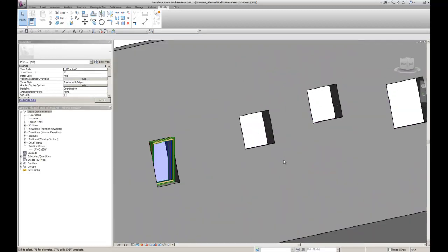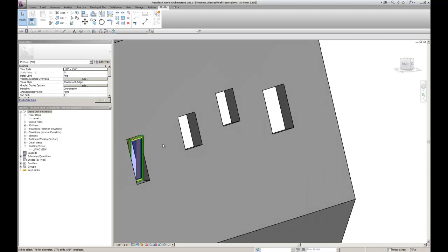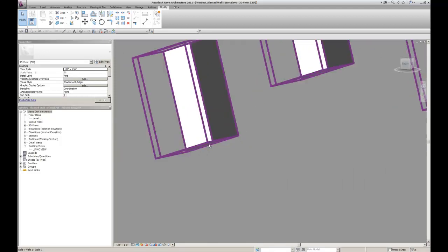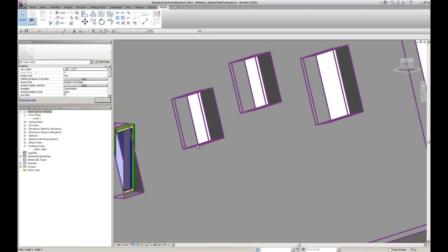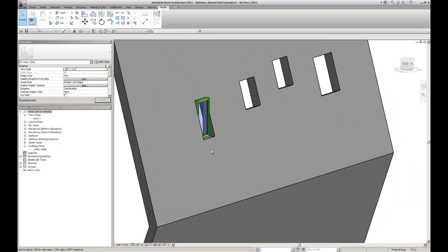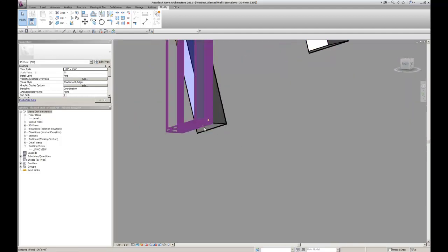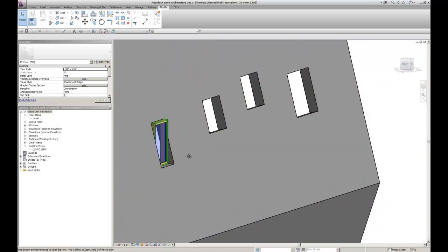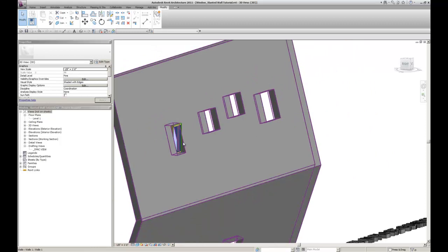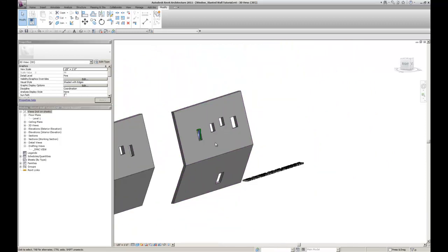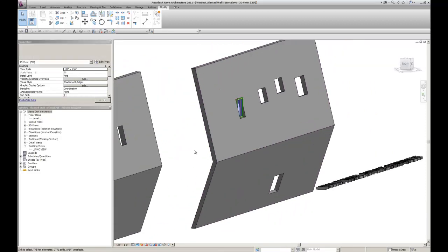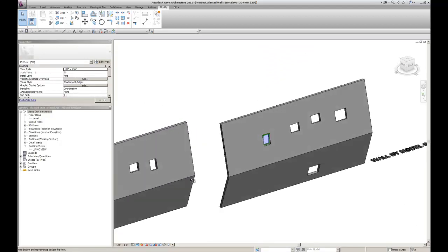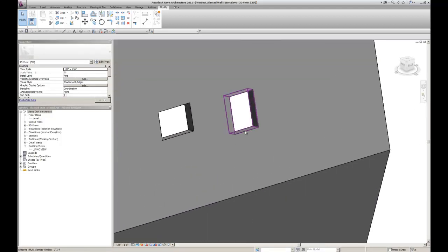So one issue to think about is that this type of family is following the angle of the face, so it's cutting perpendicular to the face. This family is cutting parallel to the ground. And it may be a combination of both that you're really ultimately after, and that'll be in another lesson how to achieve that result. But I'm going to go ahead and flesh out this window family with some glazing and mullions.